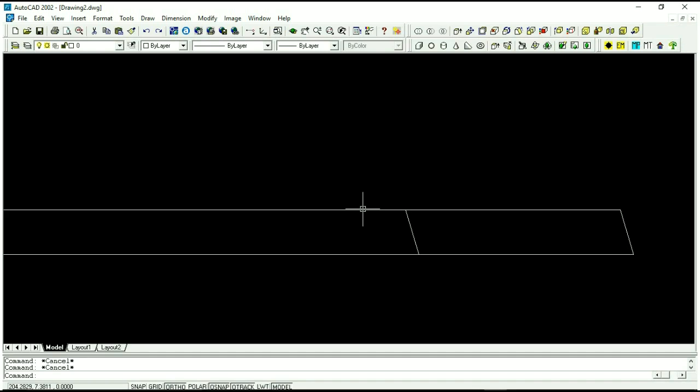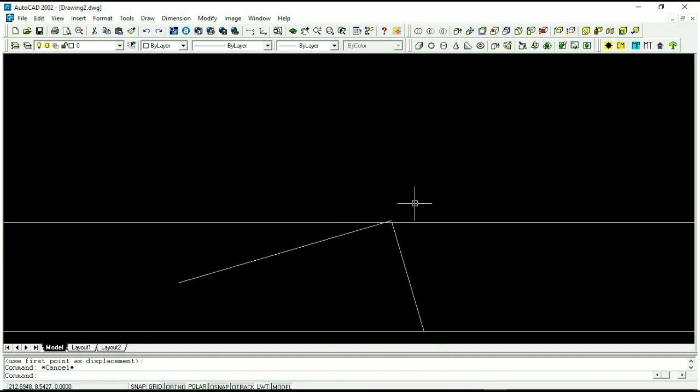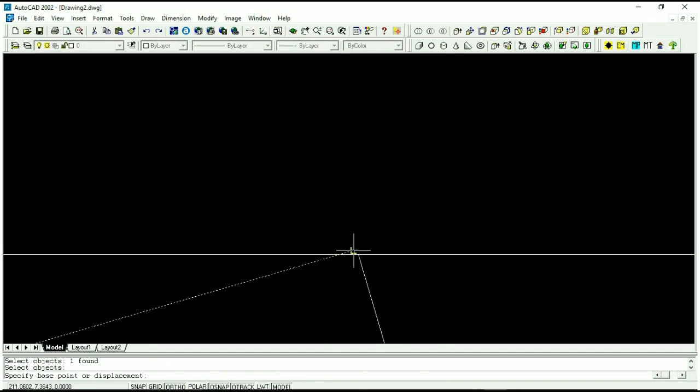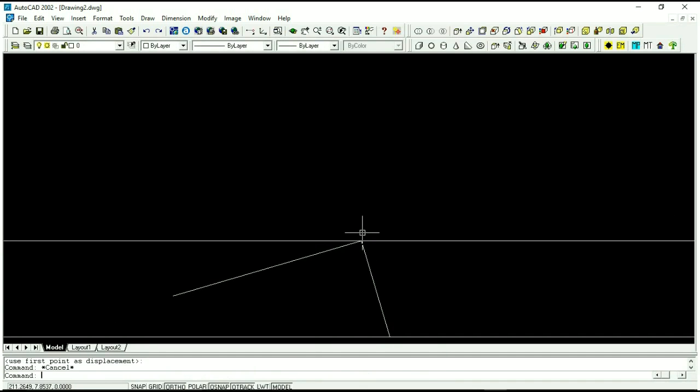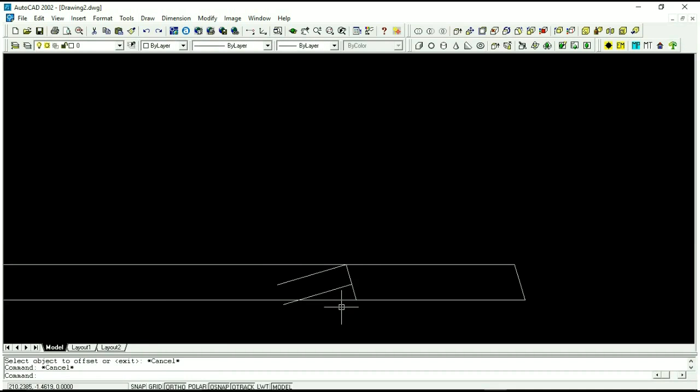So I'm going to draw a line that's perpendicular to this line. I'm going to move it up to here, and I'm going to, whoops, move it up to here, and I'm just going to make it so that the hip drop is 4.25. 0.221 is about a 1/4. So that's my seat cut. Then the tail itself extends down vertically 10 inches from the top of the wall, which is what this line represents. And that's just another trust me number, but that's typically what it would be based on how we used to frame.